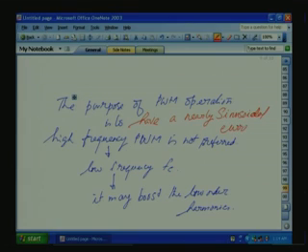Why? With sinusoidal current we get constant torque, ripple torque will not be there, harmonic losses will be less, and efficiency is more. Then another PWM scheme, which is very popular, is called current hysteresis type control. This is used in high dynamic performance applications and it is very easy to implement. So, we will talk about the current hysteresis controller now.